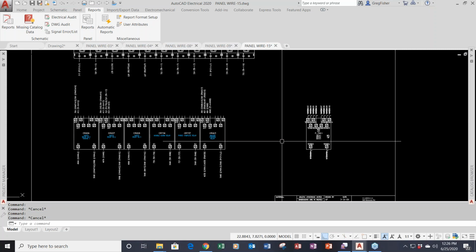If you need to display wiring information like this, I add one more step to that 4-step process. Now it becomes a 5-step process. So then I go and create a second footprint symbol. I've already created the one. I can create my new one with the wiring information based off of my original one. So yes, it will take you creating a secondary footprint symbol.